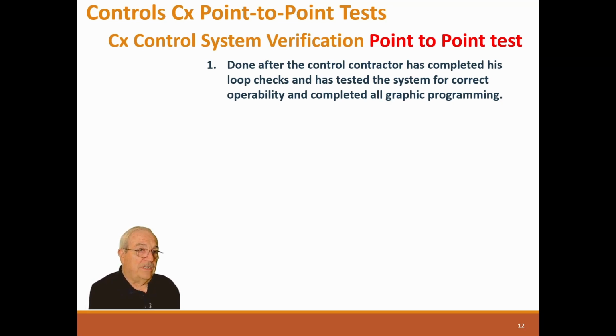So what we did to combat that, in our process, we asked for copies of each typical graphic in the control submittals. So when you submit a control submittal, you need to have a copy of every unique graphic that you're going to put on this job. And it's very wise to do that. This way, the owner can check the graphic and say, yep, that's what I need to control this job. The engineer can say, yeah, that looks like controls, and you as a commissioner can check it. And then the control contractor is in good shape.